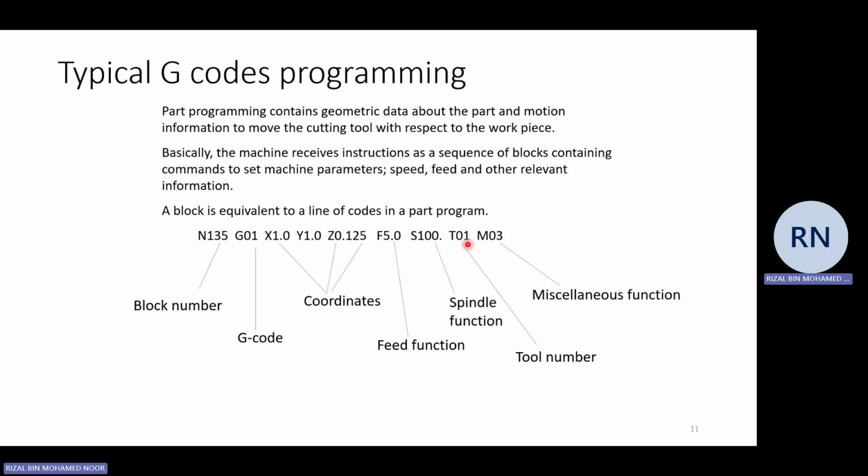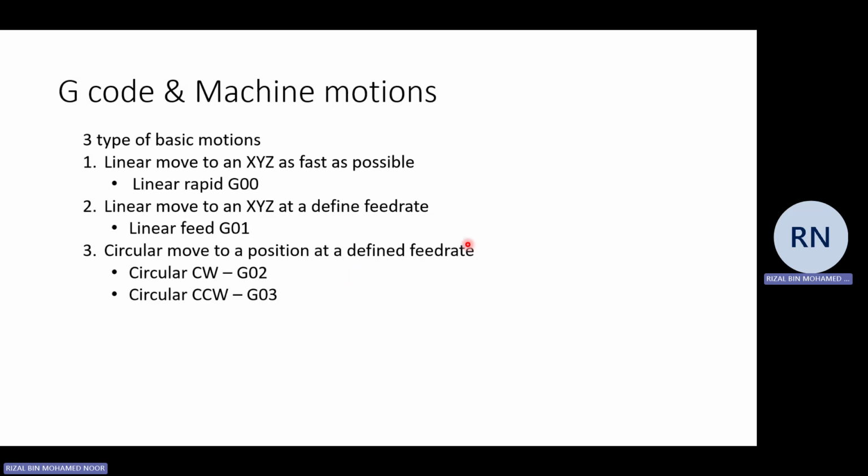It depends on the controller language. For Fanuc, we define it by tool number. For Siemens, we use a tool name. So we have a slight deviation in how we define the tool, either by tool number or tool name.